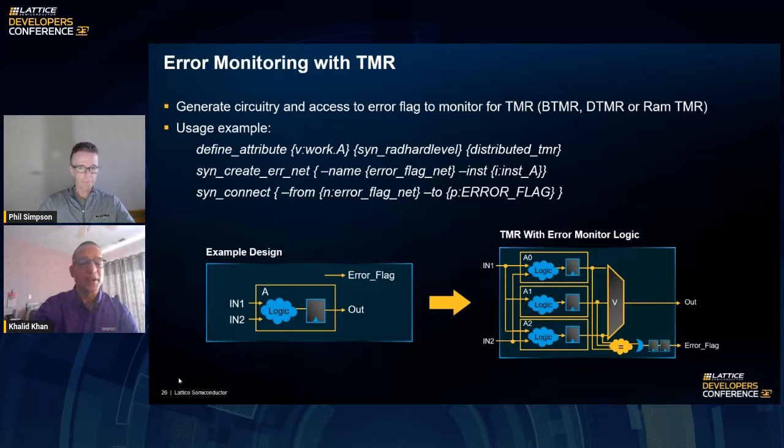Simplify provides you the ability to insert error monitoring flags on TMR instances, as well as Hamming 3 FSM and ECC memory output instances. You can insert an error monitoring flag between your design error monitoring IP in the RTL and the high reliability instance of your design, for example, any TMR block, Hamming 3 FSM instance, or ECC RAM instance, via the FTC constraint as shown below.